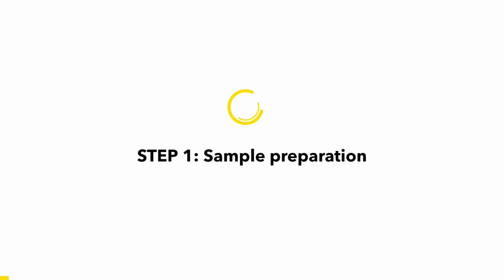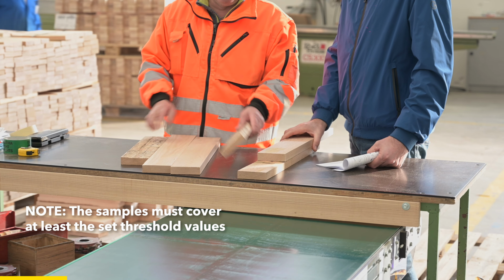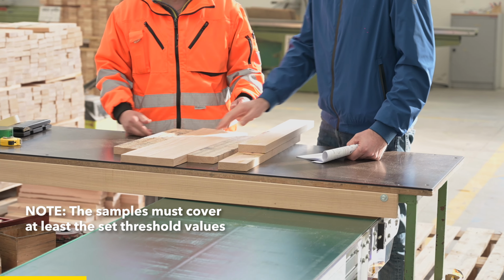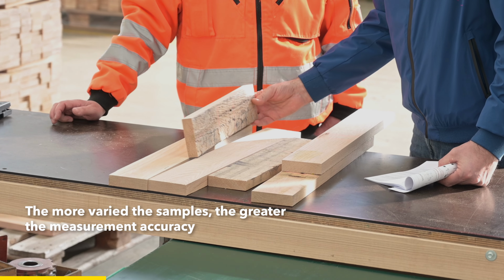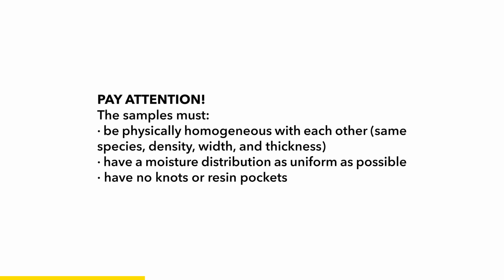Step 1. Sample preparation. Select at least 3 to 5 samples with different moisture values. Note, the samples must cover at least the set threshold values. The more varied the samples, the greater the measurement accuracy. Pay attention, the samples must be physically homogeneous with each other, have a moisture distribution as uniform as possible, have no knots or resin pockets.